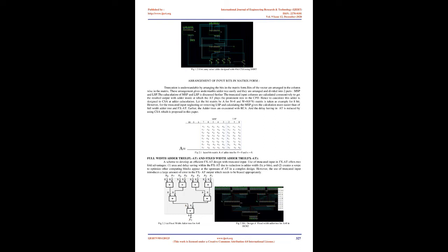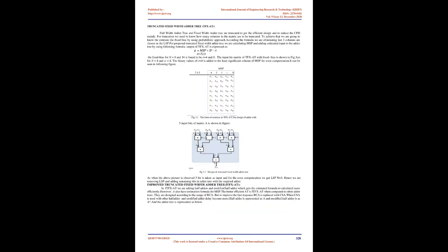Adders like carry look-ahead etc. also give lower delay, but they occupy higher area, whereas CSA gives a little less area at hardware design. Hence, when compared to our proposed adder trees, CSA gives lower delay with only a little increase in area when compared to RCA.